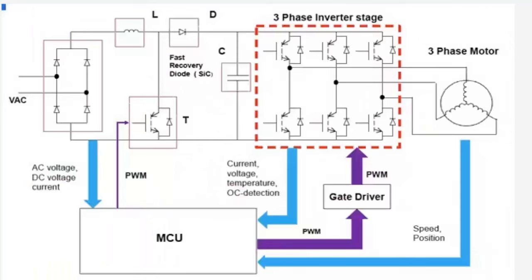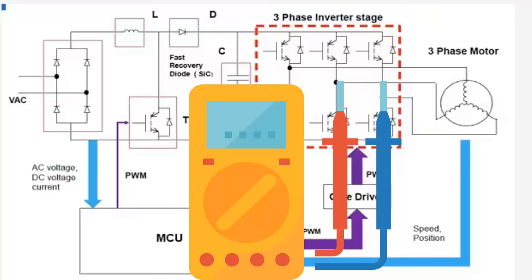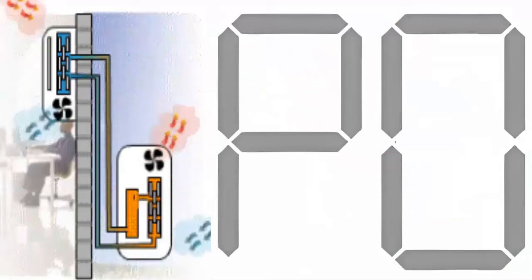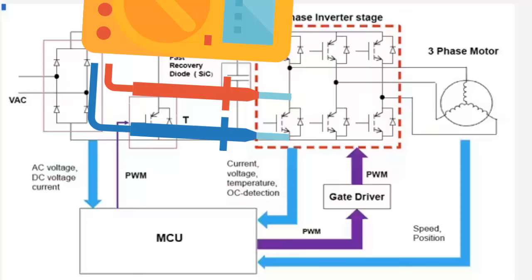11. Check the values of resistors in the IPM circuit, as well as the status of diodes, and verify the status of capacitors. Additionally, observe the state of transistors that send voltage to the compressor coils. 12. The easiest way to test transistors is to check with a multimeter the value between the transistor legs. If one leg presents different values from the others, it probably needs replacement.